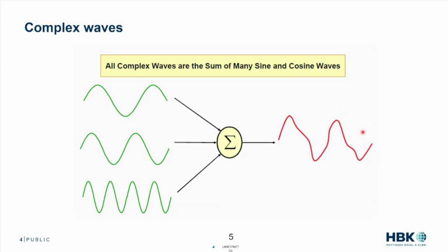This is a lot closer to the reality we deal with in motor excitation. But it's also important because we can take this motor excitation, and this is a very ugly motor wave, I know. But this is coming from a sound and vibration presentation. Fascinating how similar the two are. We can take this complex wave and break it into this element with this amplitude and this frequency, this element with this amplitude, this frequency, and this phase. And we can break it down into its individual waveforms, which I think is a really interesting and exciting way to analyze these things.